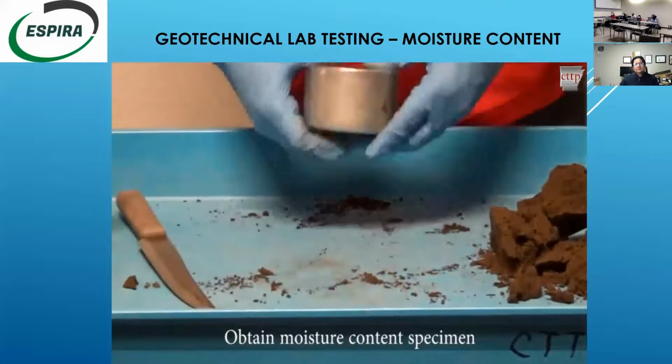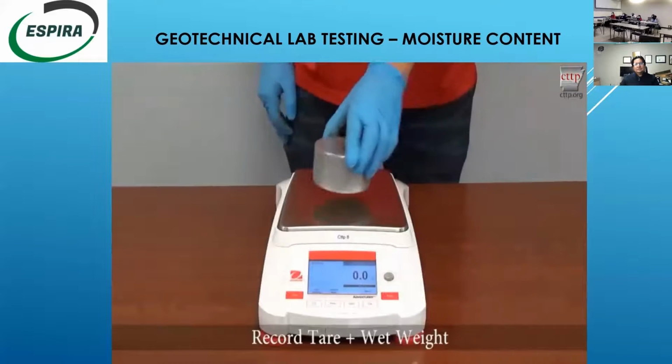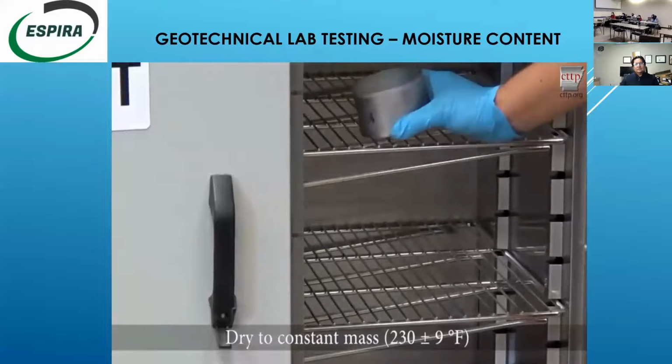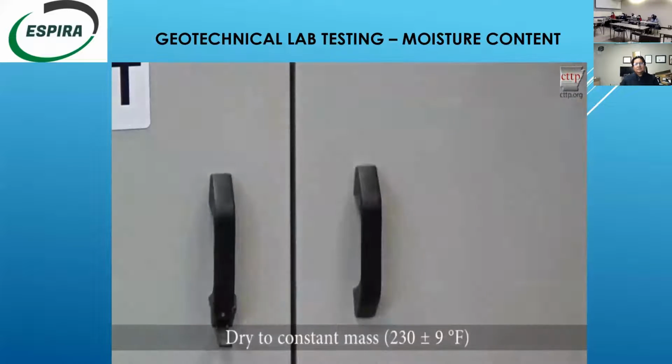Immediately cover the tin with the lid. Zero the scale and place the sample on the scale platform. Record the tare plus wet weight of the sample. Remove the lid and place it below the sample container. Put the sample, container, and lid into the oven.